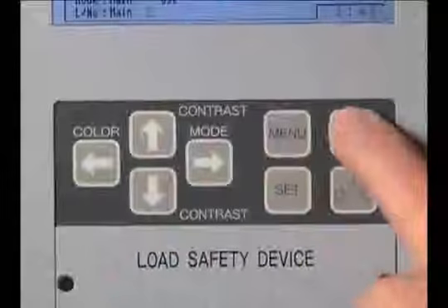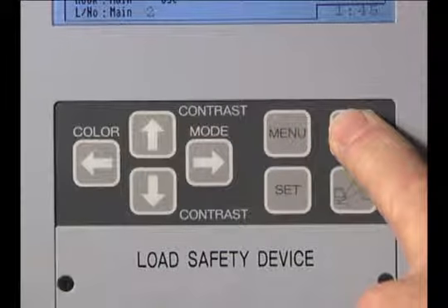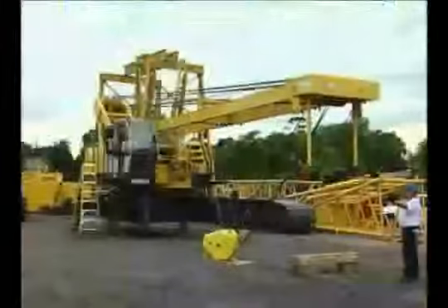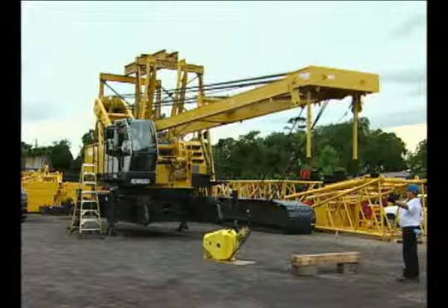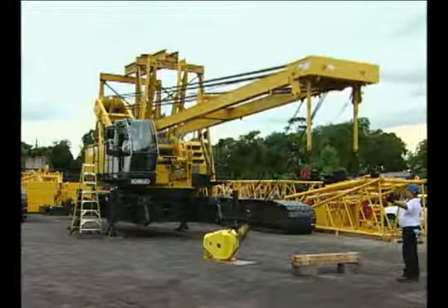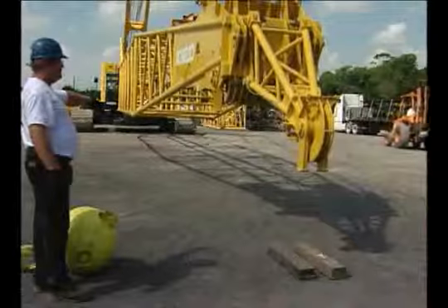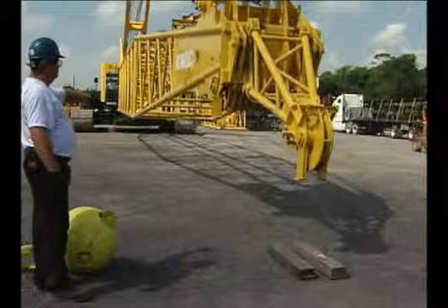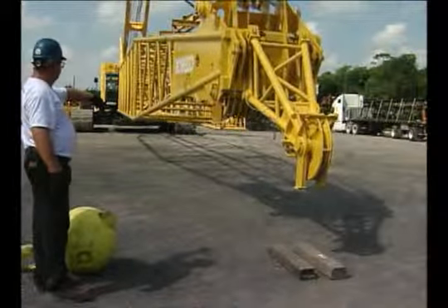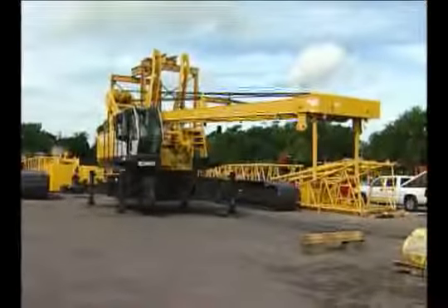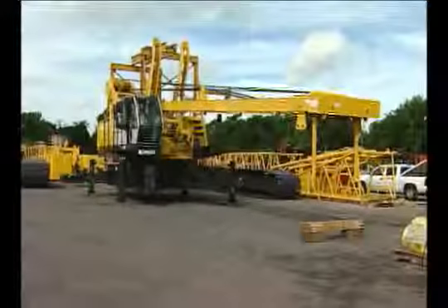The button showing the boom being taken apart will place the crane into setup mode. This will allow all functions to work during assembly and disassembly of the crane. The button showing the boom going down is necessary when the operator needs to lower the boom to the ground after the boom is out of the working radius, or to lower the mast past its working radius during self-assembly.